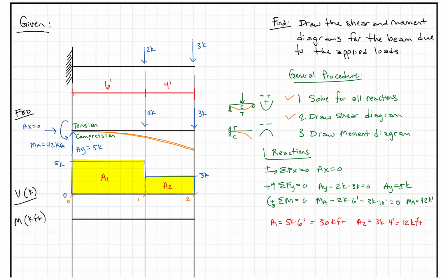So here, what we know is when we look at the moment at 0, this has to equal the moment at A. And typically with simply supported beams, the moment at A is 0. There is no applied moment. But here we have a rigid connection. If we call this point A, we have a rigid connection right at point A, and that's going to restrain rotation, which is going to cause moment. Anytime you see curvature in a beam, you can start to think there's got to be a moment there because there's tension on one side and compression on the other.